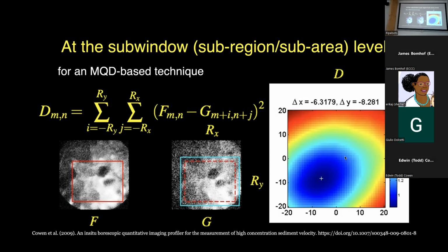And so here you can start sort of questioning, how do I track that subpixel location? You can see we're reporting displacements at a subpixel accuracy. And here we're using a center of mass technique because it turns out this has less of a bias when you have these very flat bowls. But there's always lots of questions about how you do these subpixel fit schemes to improve the displacement accuracy.